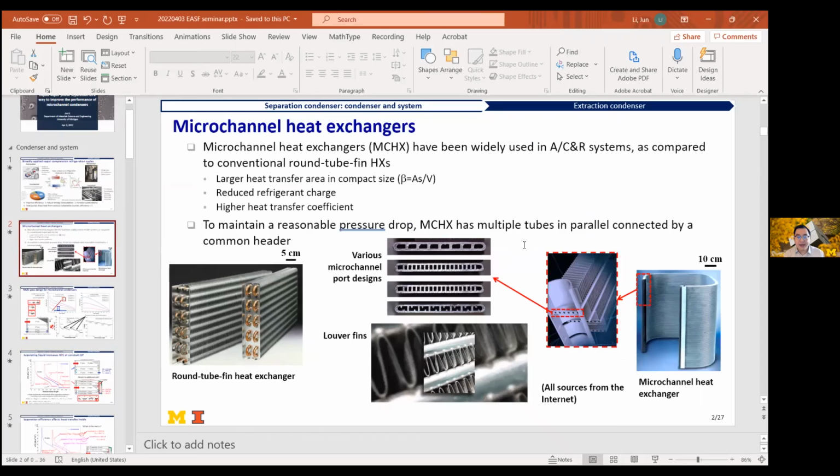With my heat exchanger, 70 centimeters wide and 40 centimeters high, it's on the order of several hundred microns. That is about the optimal size for the microchannels. But I know that, for example, for electronics cooling applications, those microchannels may be even smaller.